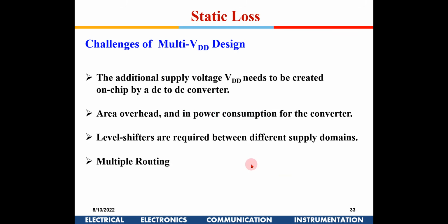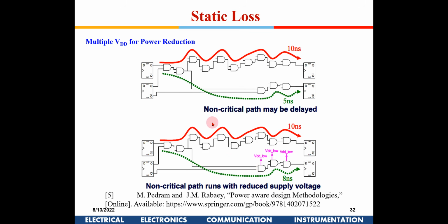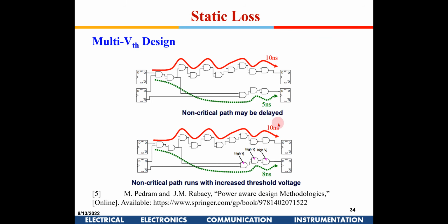But say for example, you have something known as dynamic scaling in some portions of the circuits, when they are not being used. You can reduce the VDD. That is known as dynamic scaling. That's what your laptops handle, where modules which are not used, when it is going to sleep, or some modules will be shut down automatically by reducing the VDD. So that is known as dynamic voltage scaling. Here you have a flexibility, right? You can control the VDD. Here it gets fabricated, then nothing can be done about it. So these are some of the pros and cons.